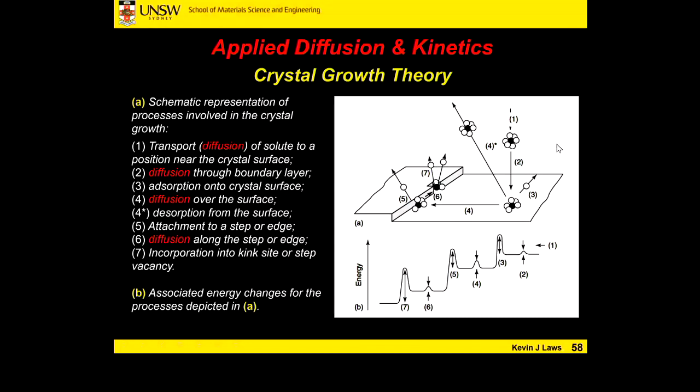Okay, so often, and particularly in solids, immediately above the surface of our growing phase, there could be things like stress fields. Okay, so in a solid-solid growth scenario, there could be a stress field from the new phase growing. That stress field could make it harder or easier for this molecule or atom to pass through this boundary layer.